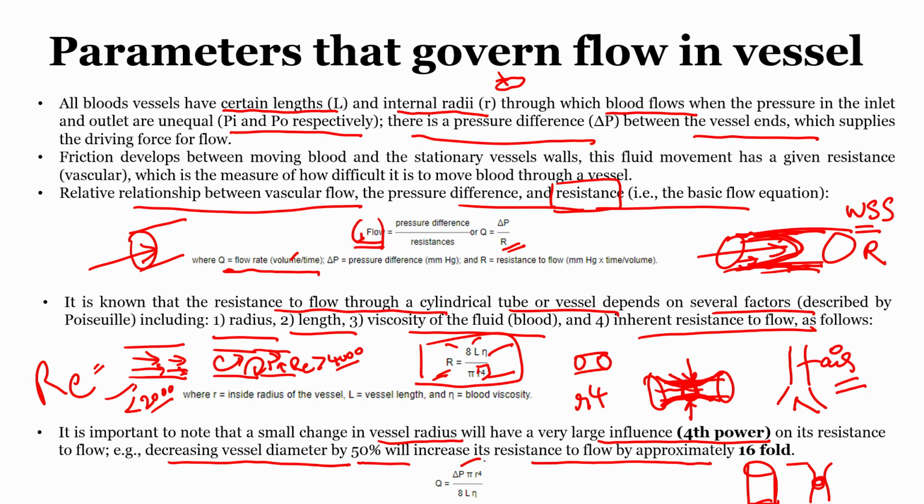Now, this is the pressure difference, the radius, and this here is the volumetric flow. How do we relate volumetric flow to the pressure difference, the length, the viscosity and the radius? This is one equation which relates the different parameters, and here this is the resistance offered to the fluid flow through a channel.